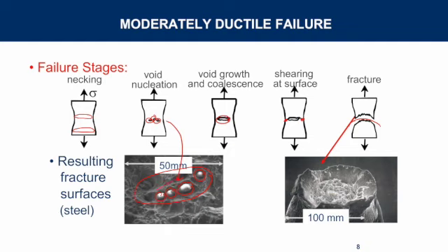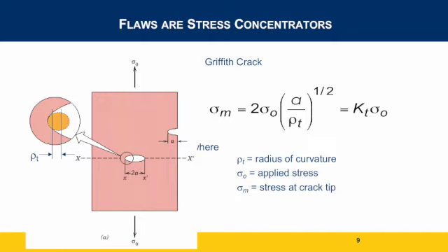These will coalesce together to form one big void, and you can see where it starts to tear apart from the other surface. It holds on at the edges, kind of like a crater. Looks like a crater, right? We've got the edges of the crater, the inner part holds on, and then the edges pull, pull, pull until it pulls apart, and you create this kind of cup shape around the outside. So that's the typical failure for metals. That's what we're emphasizing in this class.